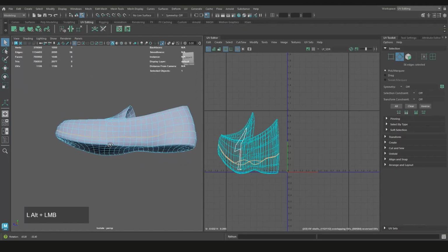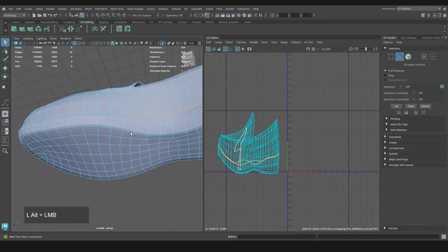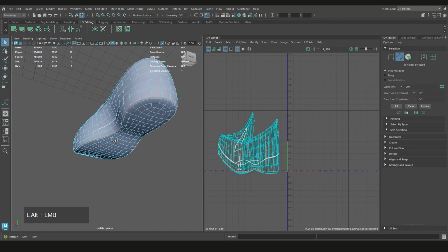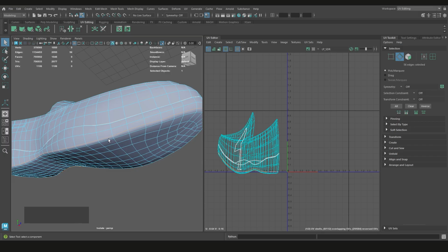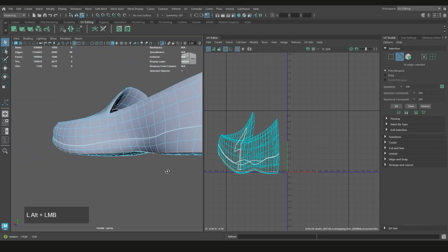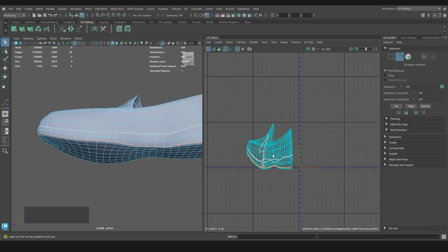And here we have to decide, okay, are we doing it over here as well? And I think I probably will. So I'm going to double click on this one. And this is why retopology is great, and this is why you don't want triangles on the edges, because this loop will get cut off if there's triangles there. So I'm going to do the same thing here, cut. Okay, if I double click here and press G, that'll just redo the last step. So G is to redo the last step.